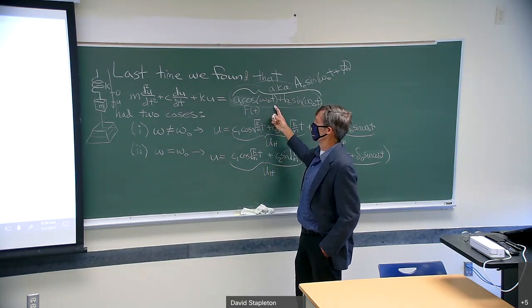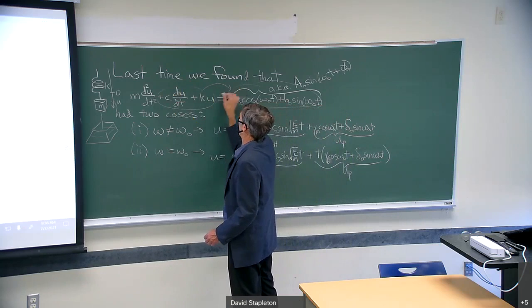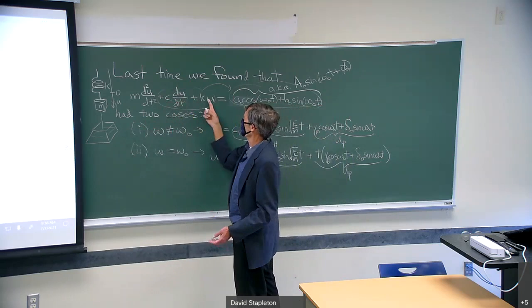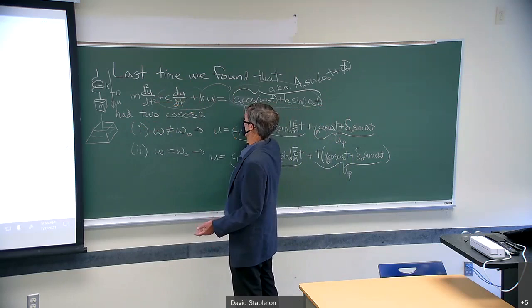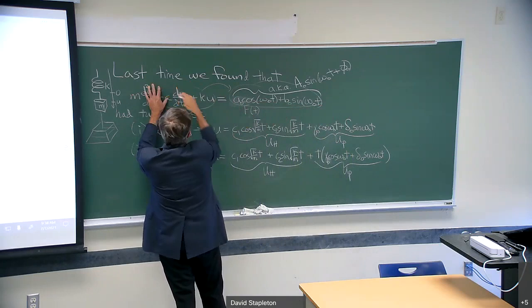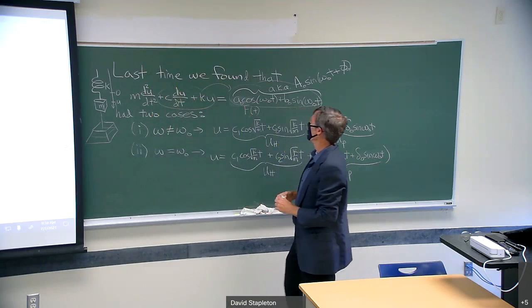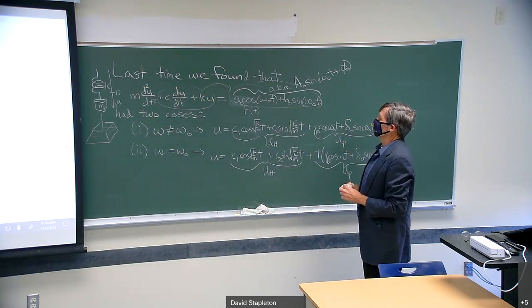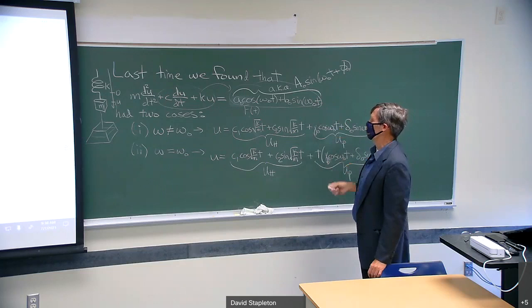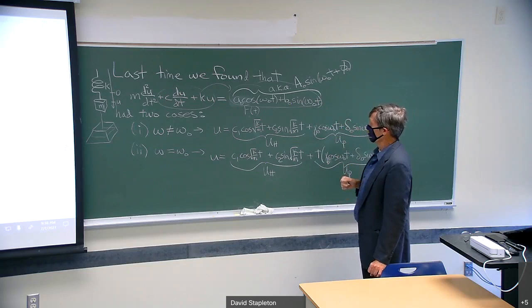It's called a forcing term because if you subtract these things over to the other side, then minus c du/dt is the force due to damping, minus ku is the force due to the spring, and this is any other applied force. This is a forcing term. It's equal to mass times acceleration if nothing else is there, and it's added to the other forces if other forces are there. So the interesting case we said is when this is sinusoidal, and this actually comes up normally in lots of electronics engineering situations.